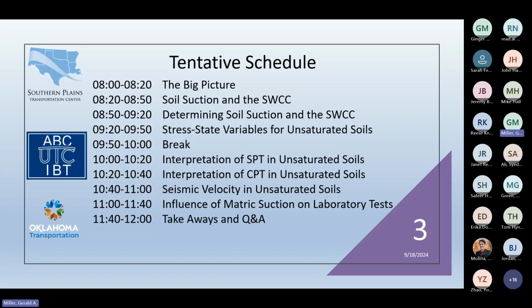Then I'll talk a little bit about how we can determine soil suction and the soil water characteristic curve. I'm also going to spend a little time talking about stress state variables, because inevitably the differences between saturated and unsaturated behavior come down to the way the effective stress changes in an unsaturated soil, whether it's wetting or drying, and the impacts on soil behavior.